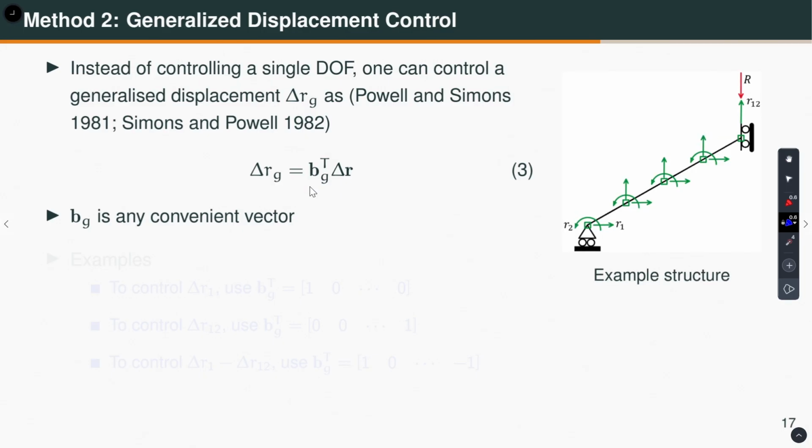So, let me give you an example. Let us say I take this structure, a beam column element, where here it is a roller and here it is a guided roller, okay. It is a guided roller, it offers only moment restraint and the horizontal restraint, and here it is only the vertical restraint. Is it stable or unstable? It is a stable structure, okay. So, I have discretized it into many elements, 1, 2, 3, 4 elements. If you number the degrees of freedom, this is R1, R2, 3, 4, 5, 6, 7, 8, 9, 10, 11 and this is 12, right.